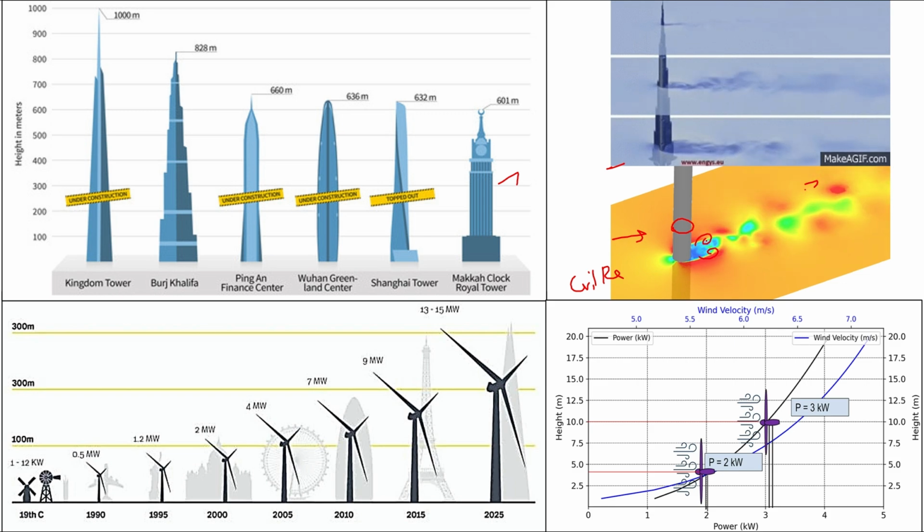Okay, and if this vortex shedding frequency matches the natural frequency of the object, then it will start to vibrate, which will lead to structural damage. So we should not reach this critical Reynolds number, to avoid structural damage.